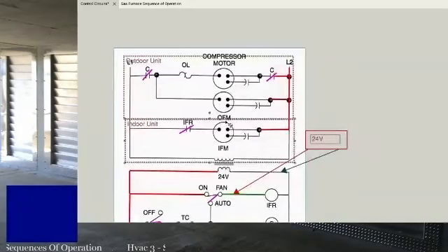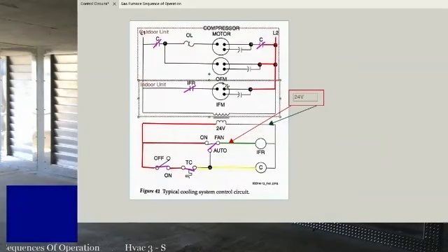So you can see, even on something that's really simple like this cooling only circuit, understanding the sequence of operations can rule out a ton of issues if you understand it before you even go to troubleshoot. So that's how you get fast at troubleshooting. As we talk about individual components, remember your sequence of operation. And if you're having trouble picking everything up, then I want you to just go A to B, follow the sequence and figure out what's wrong. Test all the individual components until you find out what's wrong.